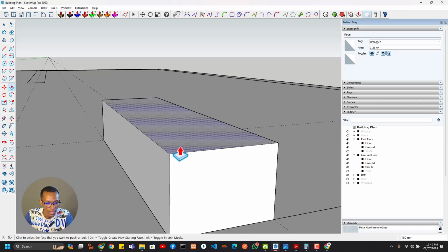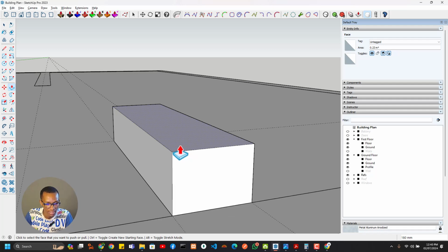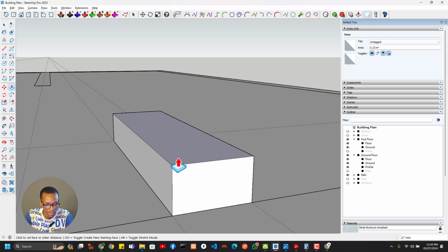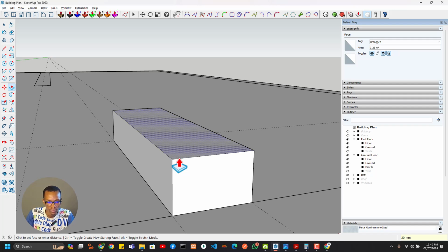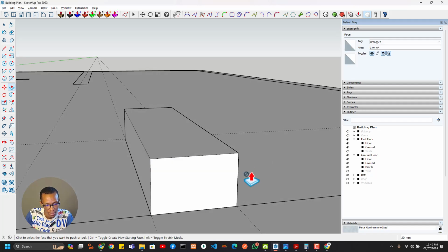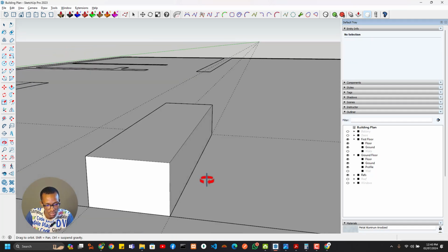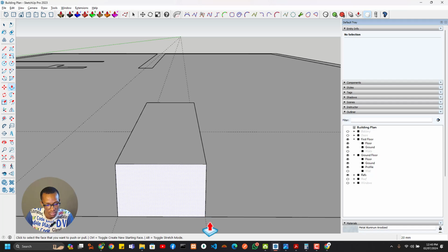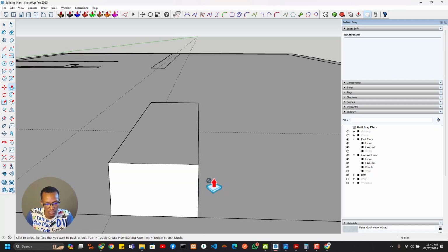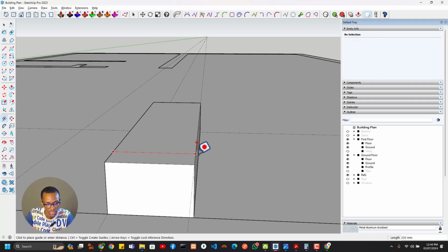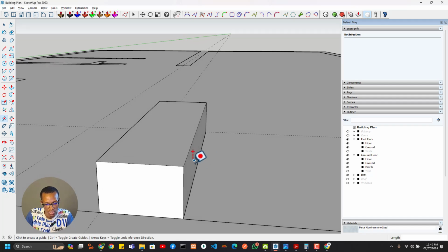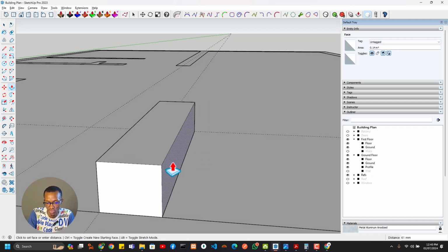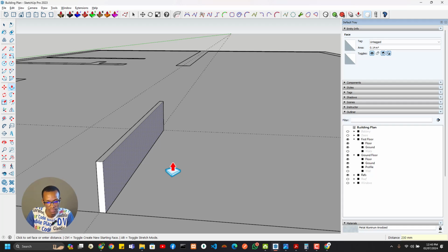So I used 180 for the riser, but here's what I'm going to do. I'm going to bring it down by 20, so it's going to be 160 high first. Then for this step, since 250 was used, it's going to be about 230.